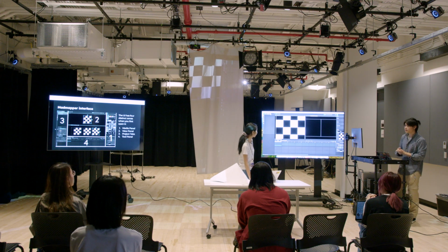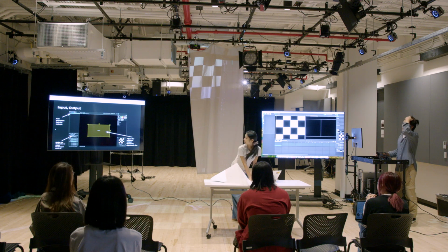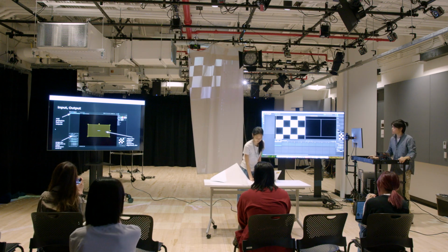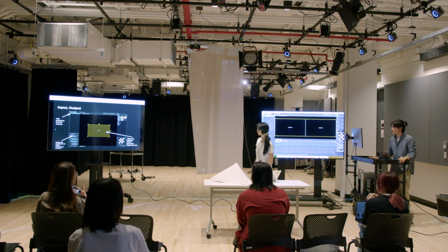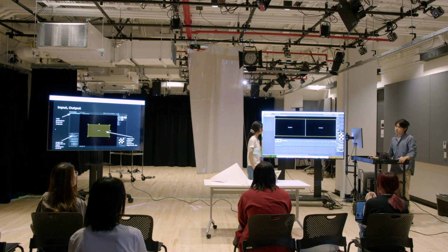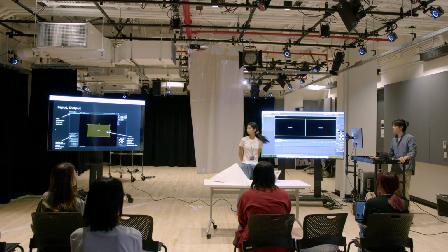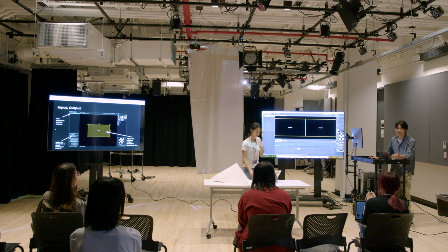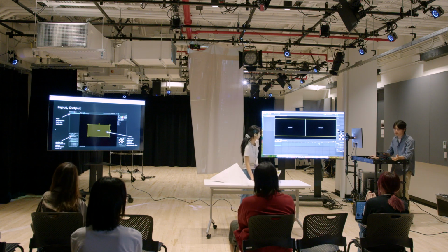But most importantly, before we start diving into MapMapper, we have to specify the input and the output. So we want to go into this tab, and this is basically where we're going to control the video outputs and the inputs. In this case, we're using 2 projectors, so it's really important to create a projector and specify where it's going to be. Oh, I might have missed this just now, but this is the scenes and cues panel, which we can also play with for different kinds of visual effects. We can close it for now.